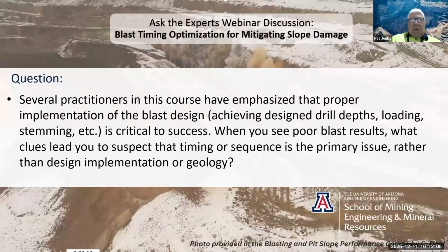Well, I guess one of the first questions I'm going to ask, going back to what John said, the phrase he used, free face. Did we shoot to a free face? Is that shot confined or over confined in some way that more energy is going to go into ground vibrations and cause damage to the wall? So that's one of the first things I'm going to look at. And it is some of the key performance monitoring tools that I look at. I love looking at the videos and watching that blast perform.